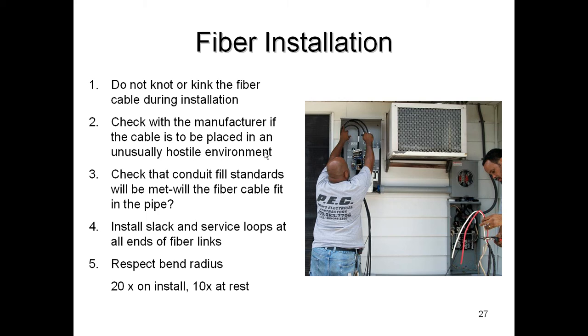Remember though, you've got to measure very carefully the length of the cable run, and if it's going to be an expensive cable run because you're going to direct bury it or whatever, buy 20% more than you think you need, because you just don't know unless you absolutely measured it exactly what the distance is, and you don't want to come up short.